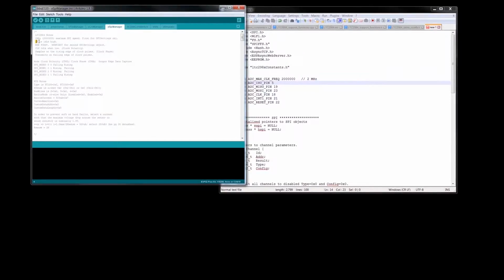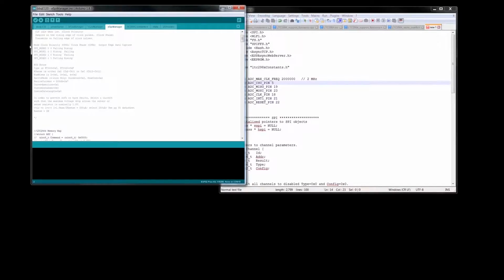Okay, so chip select is idle when high. The most significant bit is first. Clock is idle when low. Samples on the rising edge. And this is the information I got from the LTC data book, right? And these are just notes that I got from that Arduino SPI library. This is so we can set the mode later when we instantiate our version.